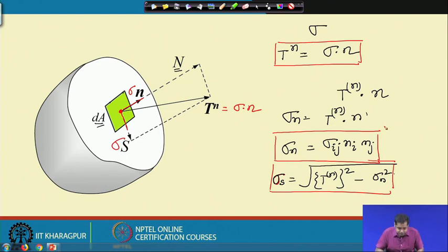Okay. Let us briefly summarize what we have discussed today. We discussed what traction is, and physically tried to understand its meaning. If we know the stress at a point, the traction can be obtained from it. Traction is essentially the projection of that stress onto a plane passing through the point, and it is obtained by the inner product between sigma and n. We also defined that once you know the traction on a plane, the normal and shear components on that plane can be determined using the projection of that traction.